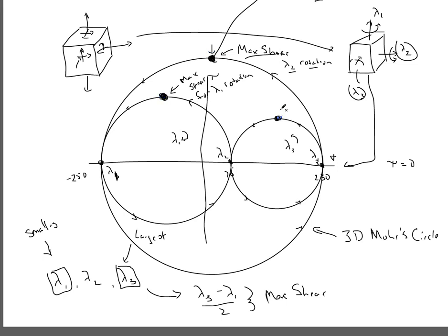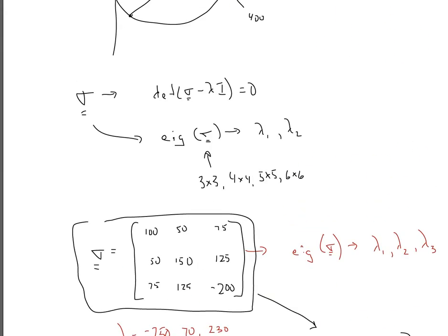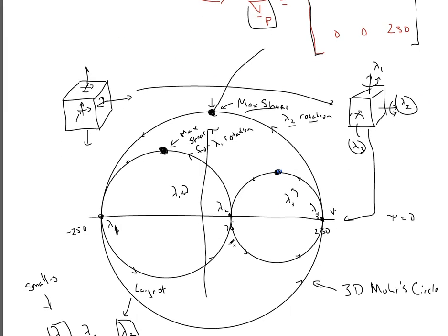So all of a sudden, those things make a much bigger impact on our material. If you think about something that's transversely isotropic, not the same in all directions, these off-axis internal shears could have a major role in whether a material will fail or not. All right, so that's really the most important lecture from the second week, this concept of the stress tensor, and how the stress tensor ends up being very, very valuable for 3D internal mechanics.